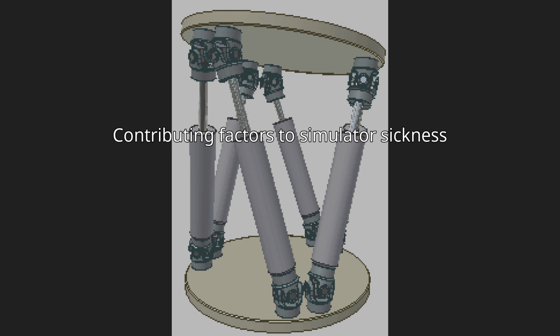Simulator equipment factors that contribute to motion sickness are quality of motion system, quality of visual system, off-axis viewing, poorly aligned optics, flicker, and delay/mismatch between visual and motion systems. The delay/mismatch issue has historically been a concern in simulator technology, where time lag between pilot input and the visual and motion systems can cause confusion and generally decrease simulator performance.